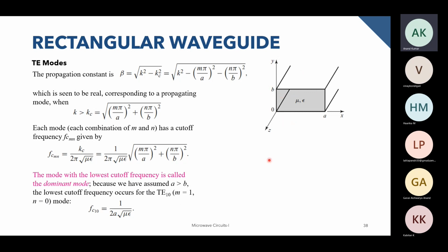So this rectangular waveguide is actually a high pass thing, and the lowest frequency that you can send through this waveguide is dependent upon which mode you're working at. This is the lowest frequency that can travel in this particular waveguide. Anything lower than this will not travel.